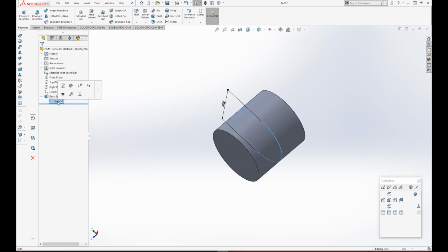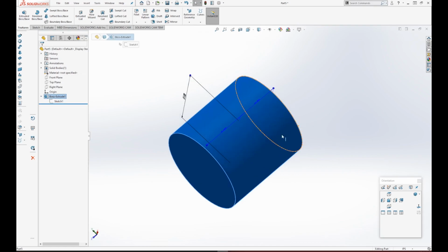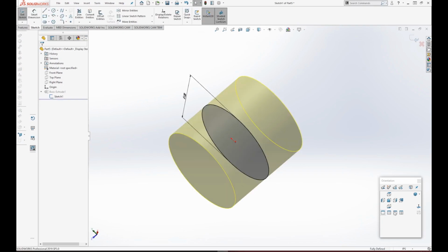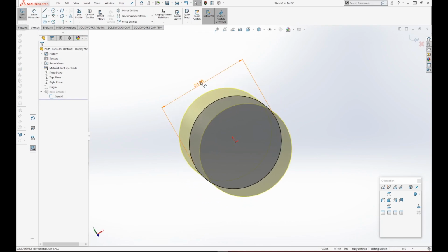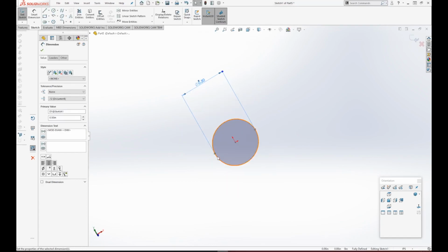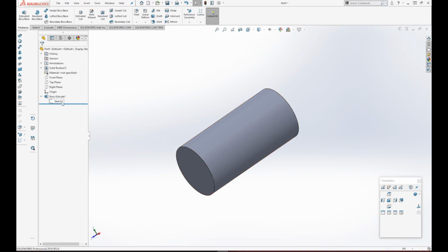And if we go ahead and click that down arrow, we can see our original sketch and our extrusion that we applied onto that sketch. So if you ever wanted to go ahead and alter your cylinder after applying the 3D feature, the extrusion on it, we could go ahead and click that sketch, and then go ahead and click that edit sketch button just as you saw. And I could go ahead and change my circle now to a different dimension, like 1/2 inch. And then we'll go ahead and exit sketch mode, and we could see that our cylinder now has updated to 1/2 inch. Now how to edit our boss extrude.